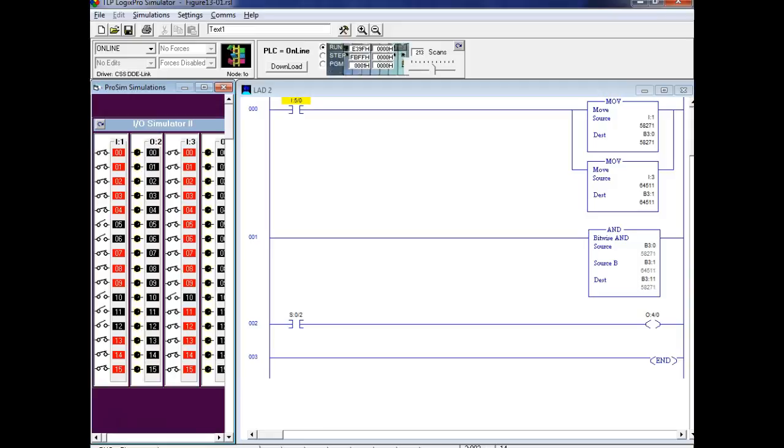So what you do is go ahead and add your first numbers like they're unsigned numbers, and don't even pay any attention to the sign. If you add your next two numbers together, then that's where you would look at your sign and at your overflows to see if you overflowed. That was a real good question.